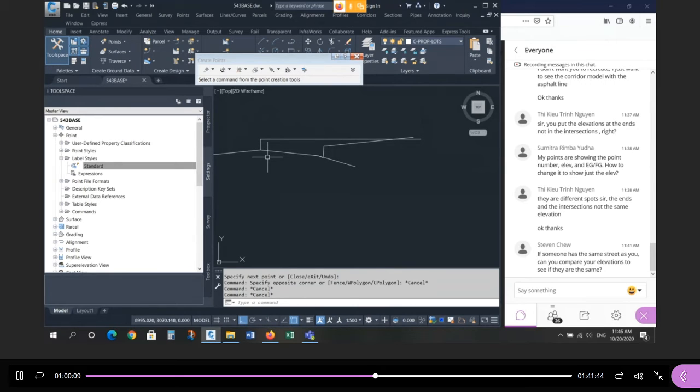And some municipalities actually write that into your standard. If you're going to propose a new subdivision, the street line along the existing rural road must be 0.3 above existing center. That's usually the rule. And if that rule is not in effect, as a rule of thumb, it usually works everywhere. So here's how you do that.